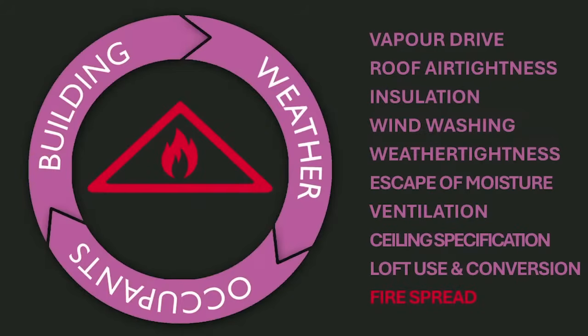Although Regulation 7, Paragraph 2 states that materials used in external walls should be of European classification A2-s1,d0 or A1, classified in accordance with the reaction to fire classification, Paragraph 3 exempts most roofs from this requirement. Regulation 7, Paragraph 3 also provides an exemption for membranes such as roof underlays.